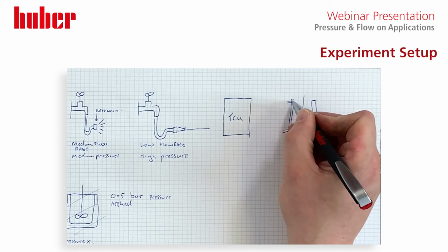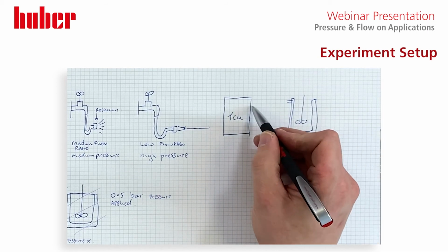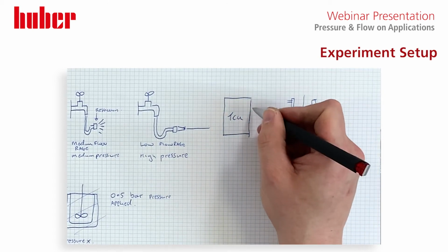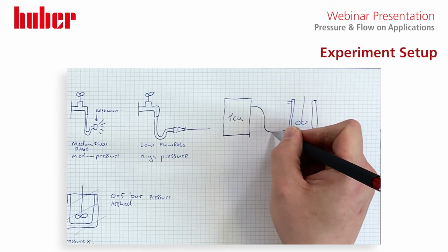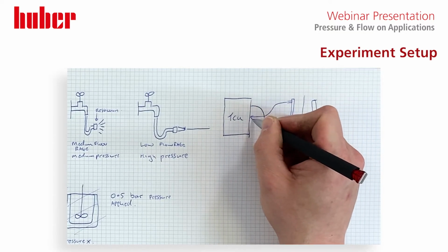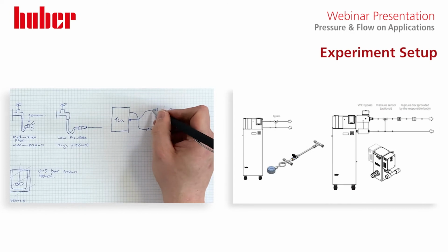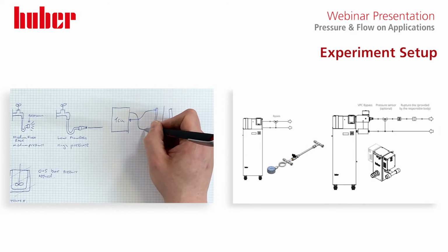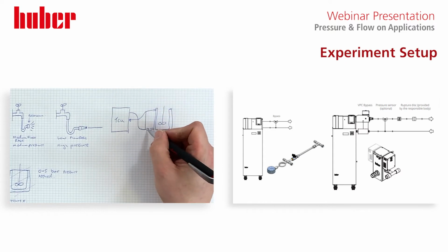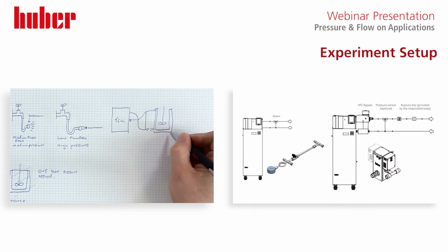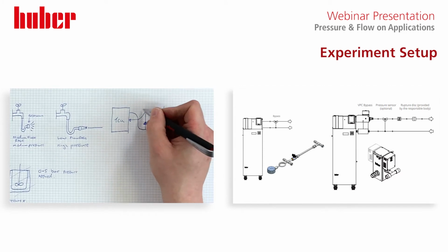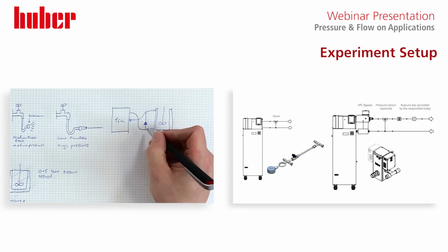Inlet and outlet. So to reduce the pressure on this, there's one option where if we draw this like this, and we do the return line going back to the unit, can we actually have any effect by fitting a bypass here? So instead of all the fluid being seen by the application, a proportion of it is bypassed and fired back up around to the TCU.